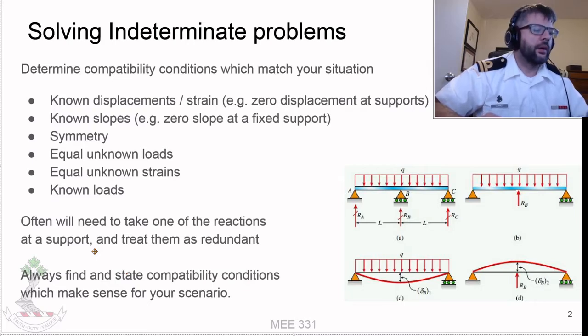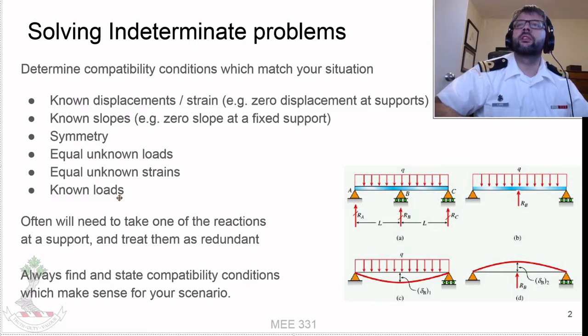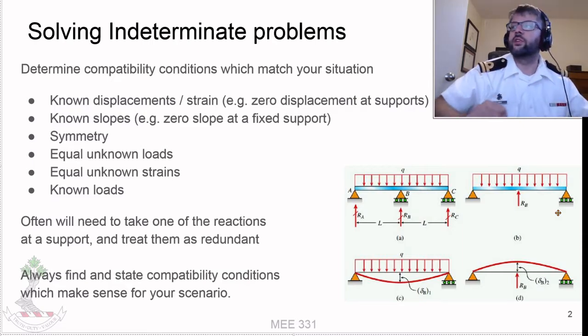So oftentimes, a technique that will need to be used will be basically we can take one of the reactions at the support and treat it as a redundant load, and then compare that to known situations.